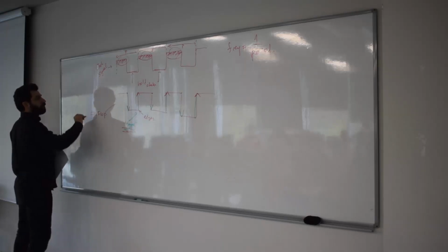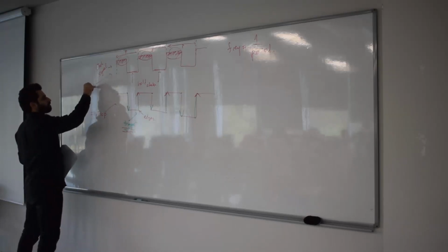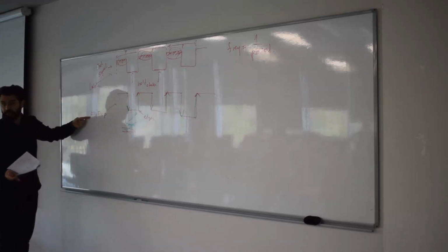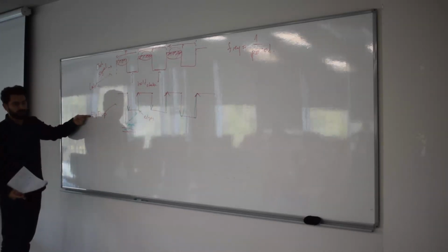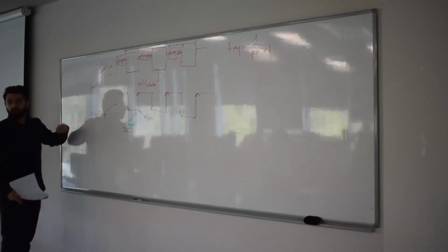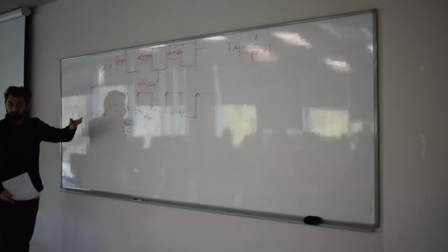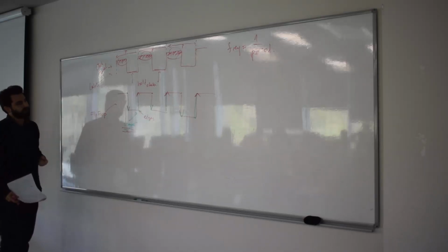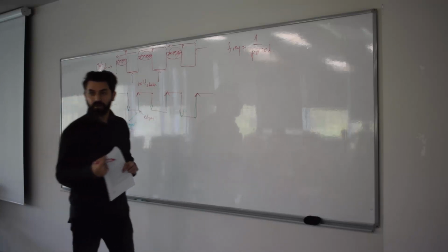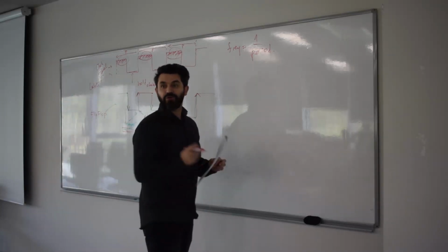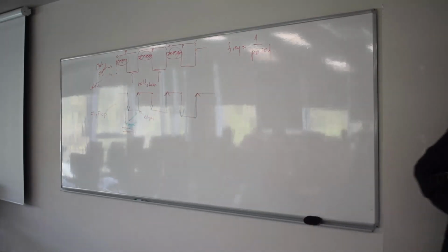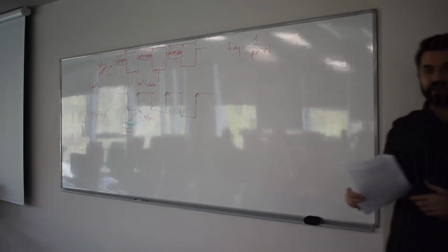Okay? Now, I'm going to draw, since you are now knowledgeable of what's happening for the flip-flops. So flip-flop, this is latch. Now you're knowledgeable about the difference between latch and flip-flop and the motivation behind using a flip-flop, the noise cancellation, right? And more stable outputs. That's also very important. Now I'm going to draw the first flip-flop of your life, which is going to be based on the latches that we already have seen. Okay? This simple D latch, which was made of 4 NAND gates, right?